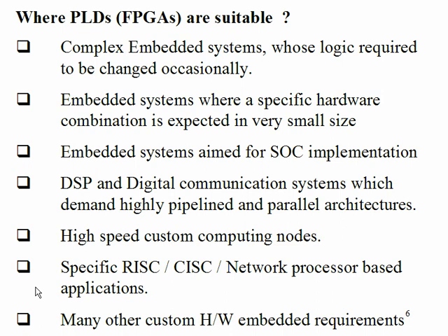See, what happens in the design of the RISC processor: because all the instructions have a similar execution time, the same amount of execution time, 2 clock cycles or 3 clock cycles, it becomes very easy to improve the performance by the concept of pipelining, by the concept of parallel execution units in the ALU. I will repeat my point. Now I am going to the designer perspective. I told you earlier about when I'm using the RISC processor assembly code, that's a different issue. Now we are talking about the designer perspective. When you are designing a RISC processor, it becomes easy for the designer to improve the speed in comparison with the CISC by some techniques. How and why? Let us discuss now.